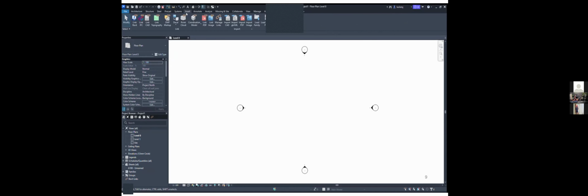We will now be looking at a demonstration of how to link models. Firstly, looking from the top to the bottom, in the second row, when you slide the mouse along the right side, you should see the Insert button. From Insert, you click Link Revit, and there you'll be able to link the model.